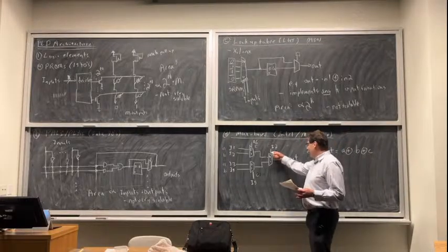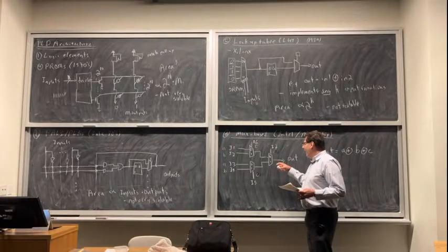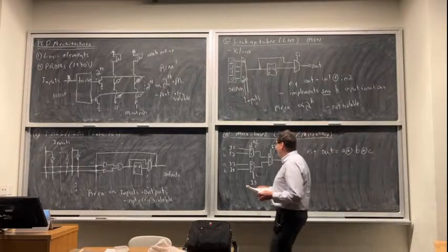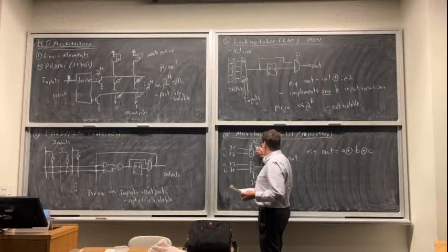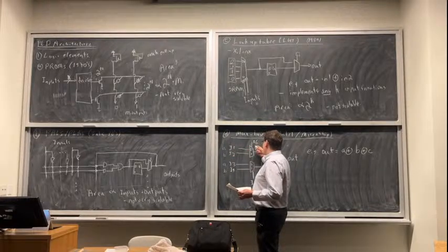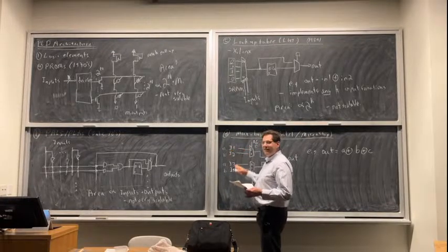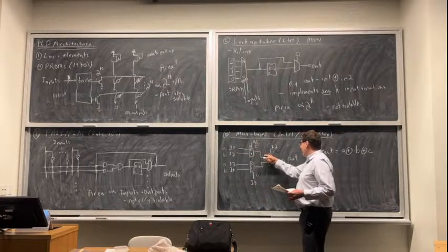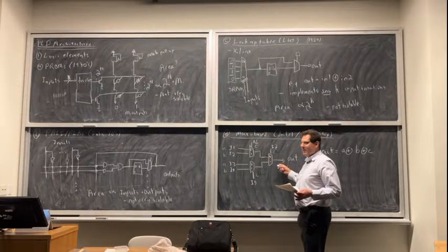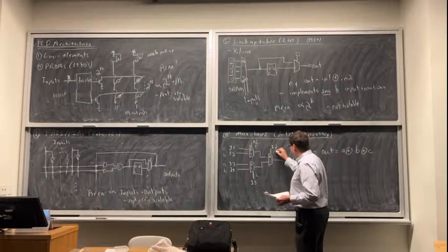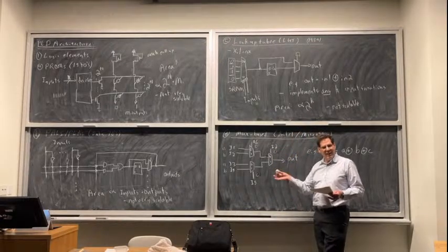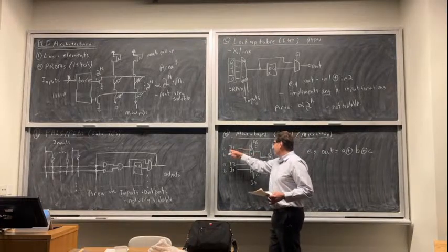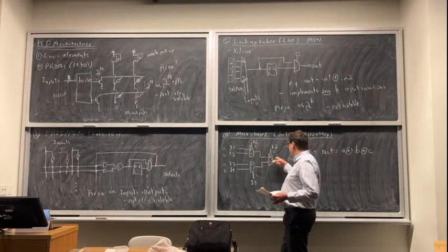So I think you're not quite sure what to put here. It's the right idea, but I don't think it's quite working yet. We can just walk through it. Let's say A is 1 and C is 1. Okay, so then, well, let's say C is 0 and A is 1. So then I would get a 1 flowing through to this point, and I'm not quite sure what to do. But in that case, it would be fine even if I tied 0 to here. So that case works. If B is 1, and A is 0, and C is 0, it works again.